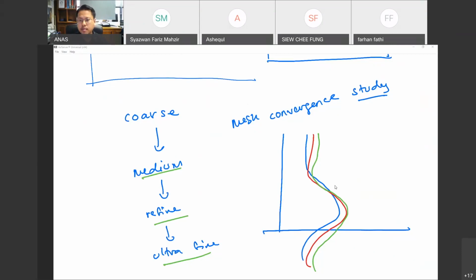So you try with the general setting, and then after that you start with a smaller value, and then smaller, or maybe one value that is larger than the first value to check, because most of the time you will see the difference here, the difference in characteristic. Right. So this is just an example. This is for the mesh convergence study.